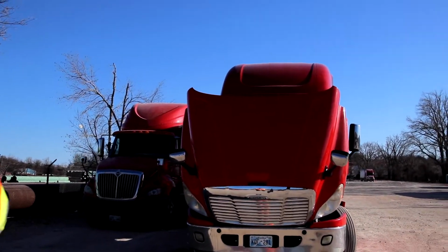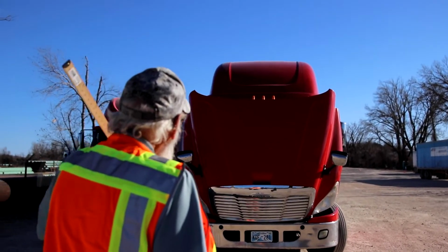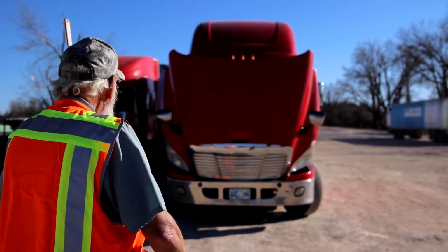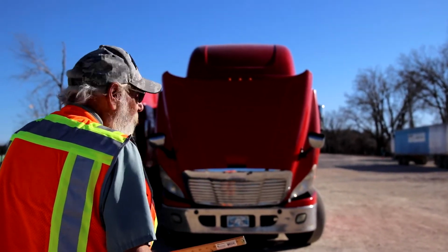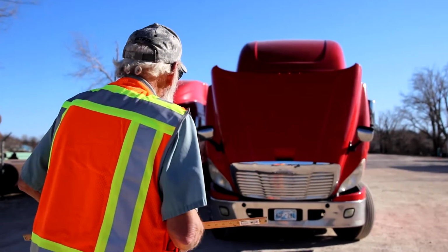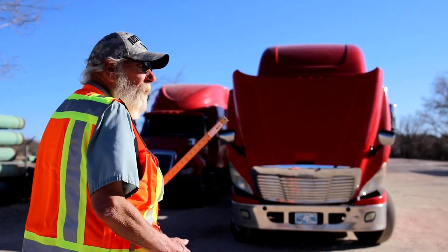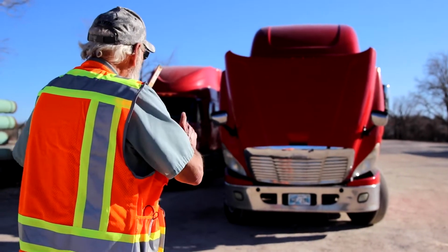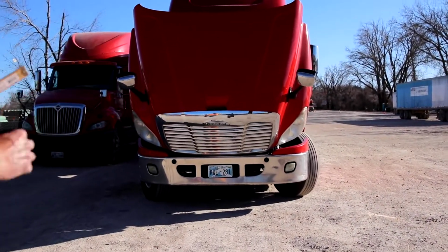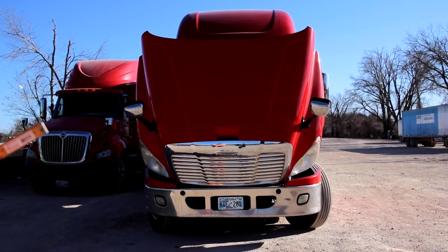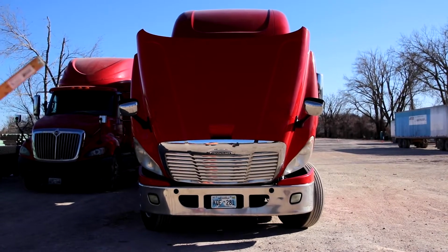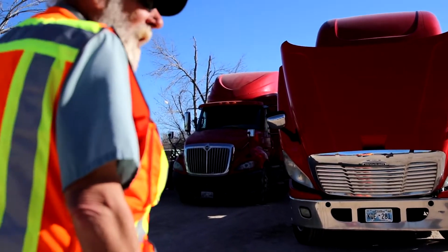Then we're going to start at the top. You have your clearance lights at the very top on the sun visor. They're amber in color. They're mounted securely, not missing, damaged, or broken. You have your fender mirrors. They are not missing, damaged, or broken. You have your headlights, left and right, high and low beam, clear in color, not missing, damaged, or broken. You also have a set of fog lights. Doesn't matter if you mention those or not. You have your left and right turn signals, your driving lamps, and your 4-way flashers, which should be amber in color. They're not missing, damaged, or broken. We will now go over here to the right-hand side.